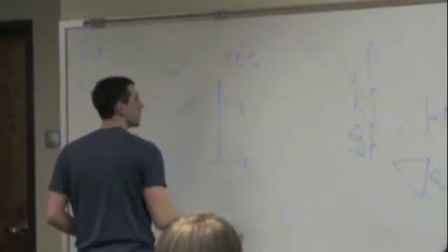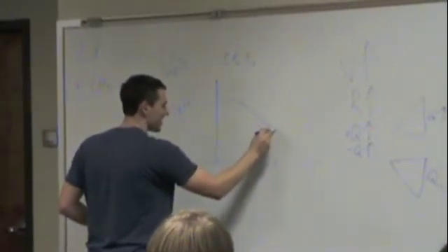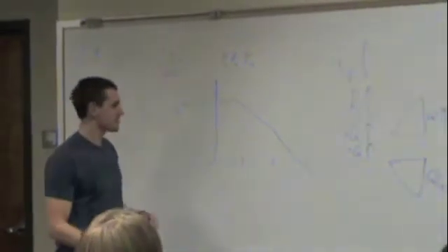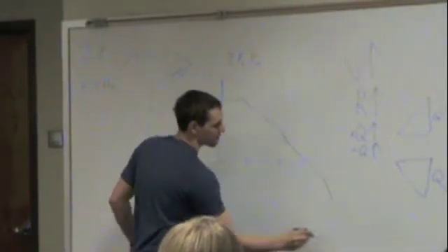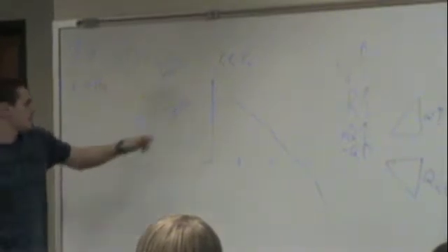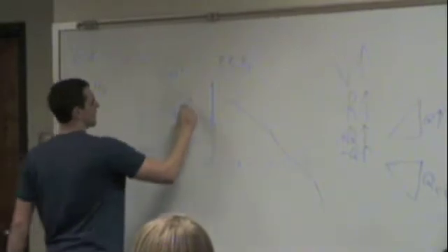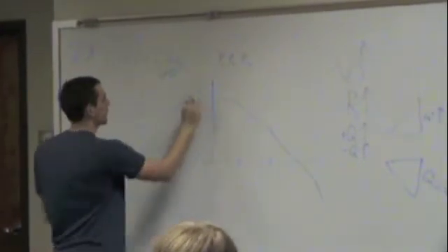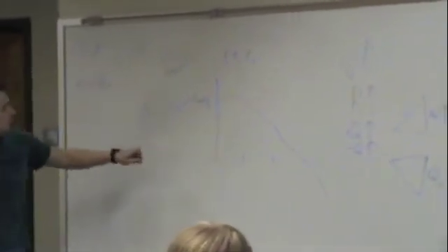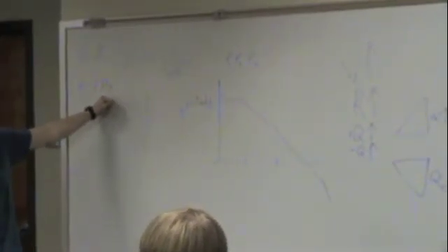Whoa, I can't draw. Thanks for the confidence. It's going to go like this. You guys remember this? And then it's going to go even steeper because it's the third pole. So if we just have one pole, it's going to stop at that. It's very simple. There's just one breakpoint, which is 10 to the 3, except like Tim said, it's in radians per second. Right? So we need to convert that into frequency in hertz. That's the problem. What do we do?